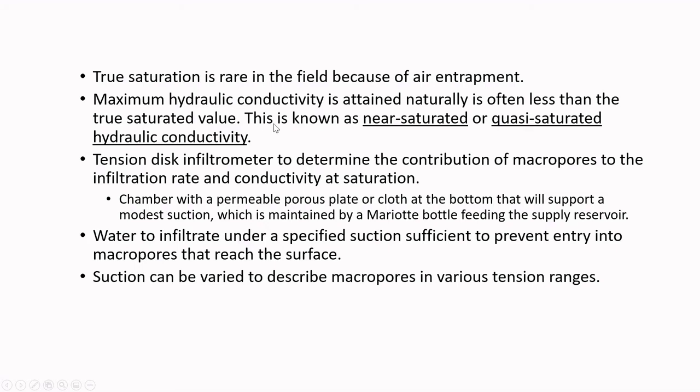This is known as near-saturated or quasi-saturated hydraulic conductivity. So we can never achieve the real hydraulic conductivity. The measured value of hydraulic conductivity in the field is less than the true saturated hydraulic conductivity value.